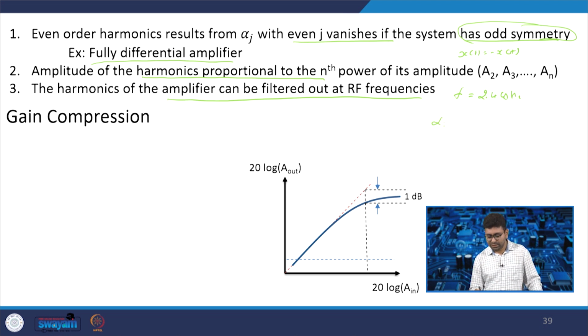If alpha 1 alpha 3 is greater than 0, that means there is an expansion. But as far as an amplifier is concerned, we mostly consider the compression, where alpha 1 alpha 3 is less than 0, because the amplifier is going to provide you the stable analysis or stable gain, and here the product of alpha 1 and alpha 3 is less than 0.